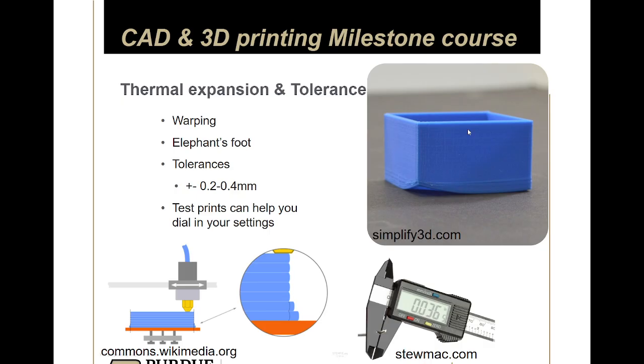So you'll see a lot of people add a bunch of fillets in that direction, then add a bunch of chamfers in the Z direction. Like in X and Y, you'll see a lot of rounded features, and then in the Z direction, people make chamfers instead of fillets.